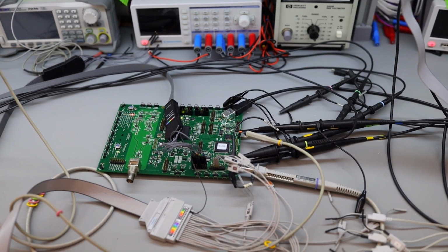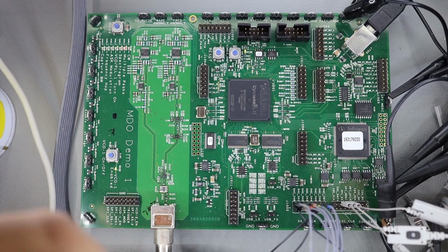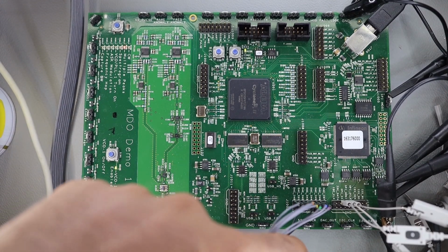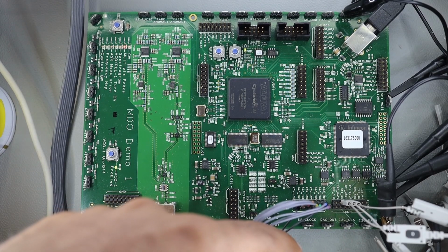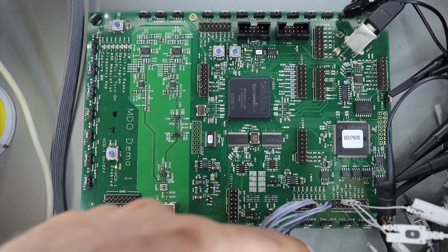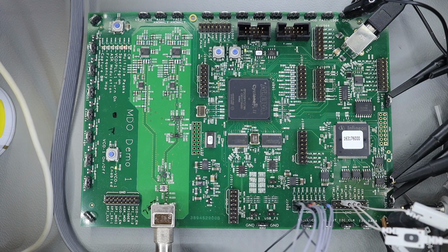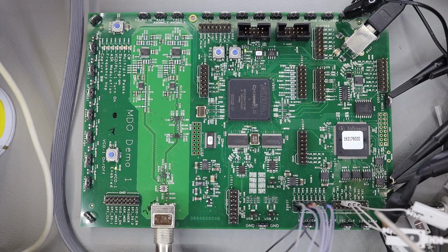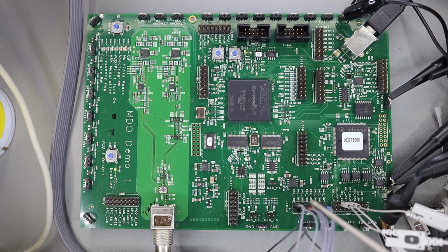This is how all the probes are connected. They are all connected to this green PCB in the middle. Just to take a closer look at the board, the slow signals start from here, and you see there is an SS clock, DAC output, I2C clock, I2C data, and on the right side, maybe I'll remove some of the oscilloscope probes. There is an SPI clock, SPI slave select, SPI MOSI, and on this little header you again have all the signals combined. These are the raw DAC data, digital values.